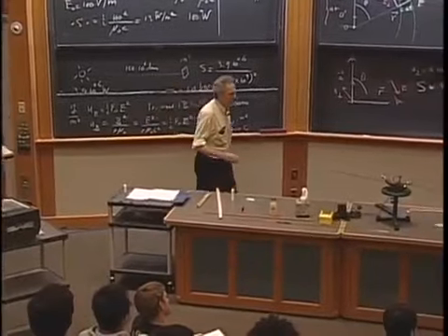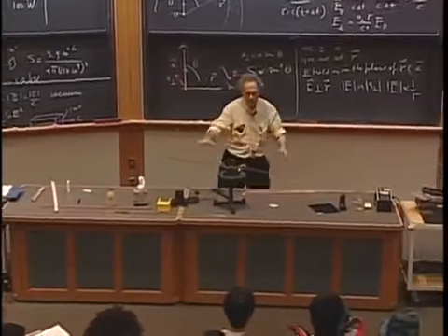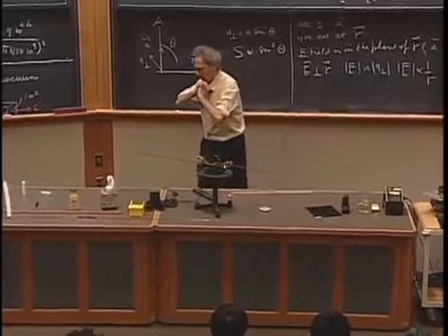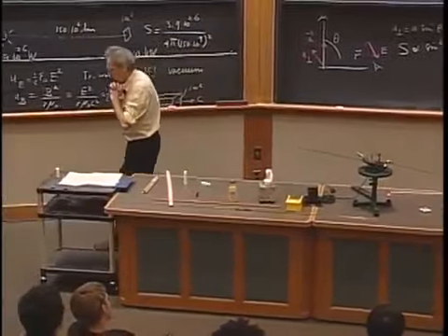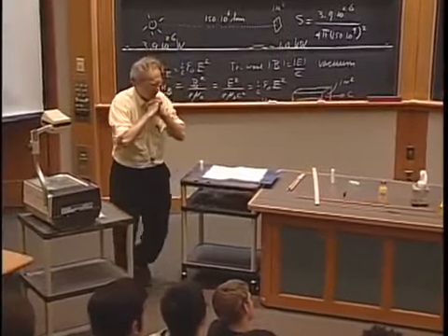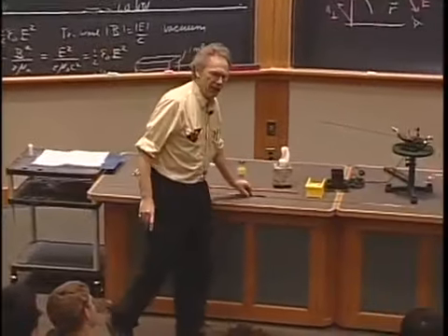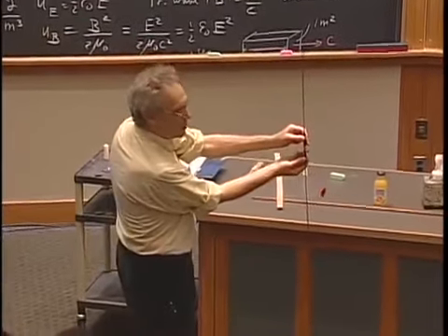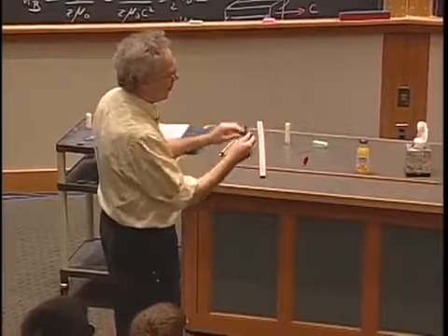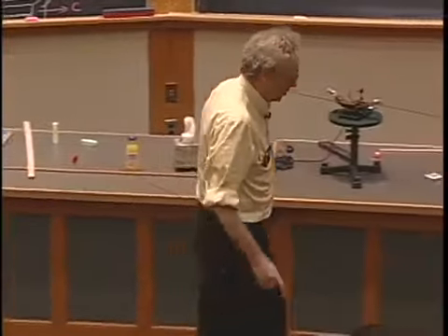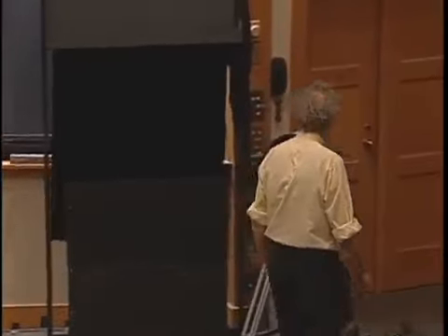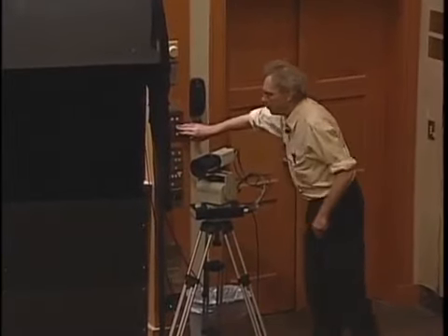We have here an 80 megahertz transmitter. We've seen that before, wavelength 3.75 meters. And I demonstrated this before to show you that the radiation is linearly polarized. And I demonstrated it by having this receiving antenna and by rotating it like this when the light went off and rotating it like this when the light goes on. Today, that's not my objective. Today I'm interested in the sine squared theta term, for which I need a little bit of assistance from someone.